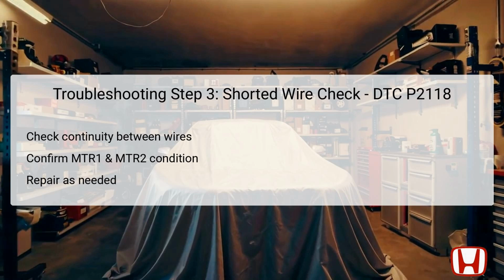Begin by ensuring that the ignition is off and that both the PCM connector C (49P) and the throttle body 6P connector are still disconnected. Measure the continuity between test points 1 and 2 within the MTR1 and MTR2 circuits. This test will help you determine if there is a short between these two lines. A strong continuity reading indicates a problem.